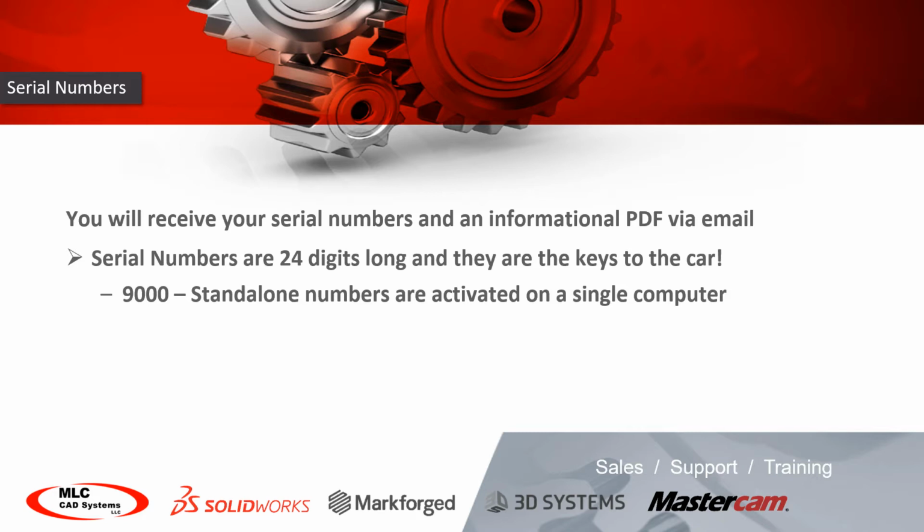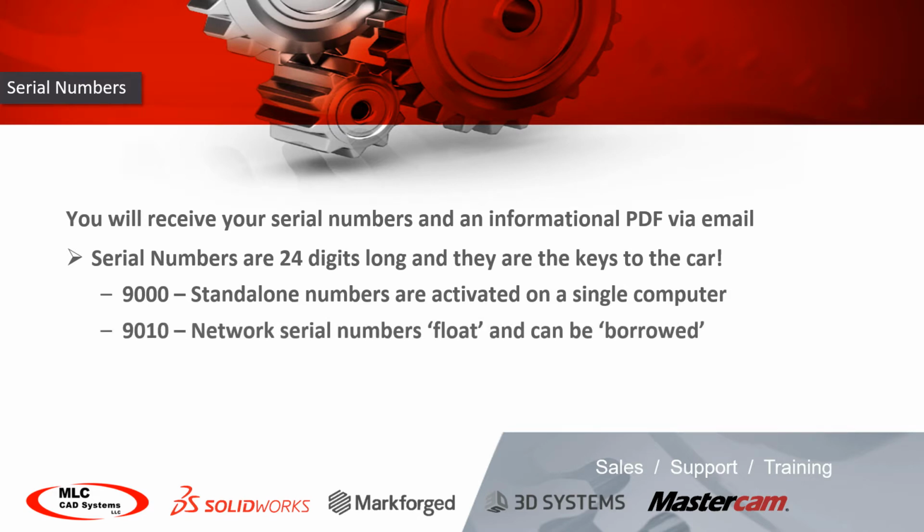So when you install SolidWorks with your serial number and you launch it the first time, it gets activated on that specific machine. Another type of setup would be a network serial number starting with 9010. This may get activated on a server or central machine, and other machines, when SolidWorks opens on them, asks that machine if there's an available license. So they can float around a network. Maybe you have 10 engineers but only 5 use SolidWorks at one time. You can also borrow a license from those types of network and go on travel.